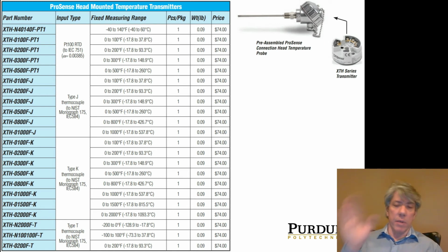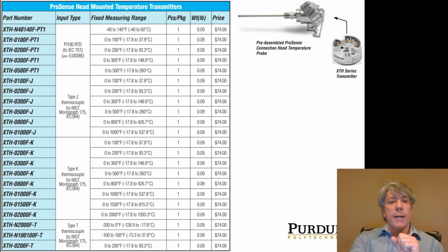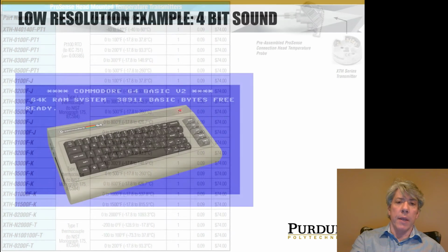The Type K thermocouple is the same in both cases, or as far as we're concerned at this point they are. But the point is this transmitter does the job of converting the thermocouple signal into a signal that the PLC can actually take in on a standard analog input channel. And there's several other devices that I've ordered that we will connect to the PLCs as well.